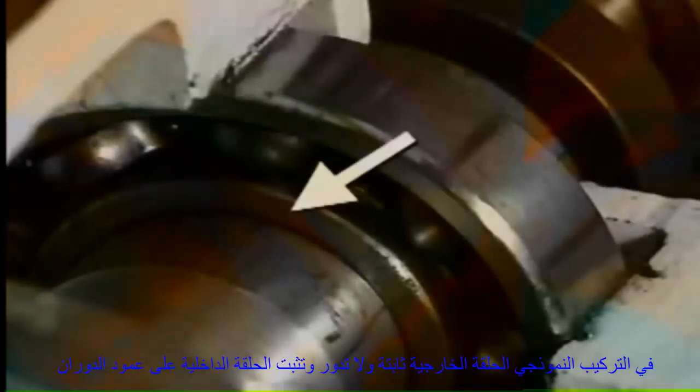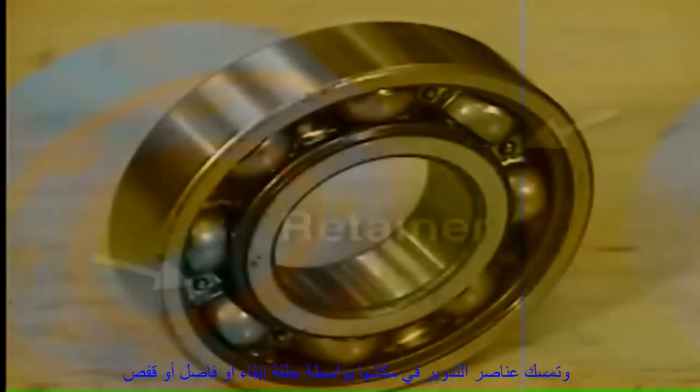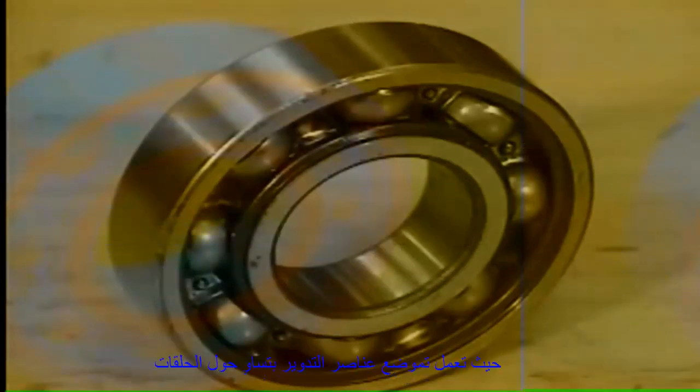These rings are often called races. In a typical installation, the outer ring is fixed and doesn't move. The inner ring is fitted to the shaft. As the shaft rotates, the inner ring also rotates. The rolling elements are held in position by the retainer, which you may hear referred to as a separator or a cage. The retainer positions the rolling elements evenly around the rings and ensures that the load is distributed equally on each rolling element when the shaft is turning.